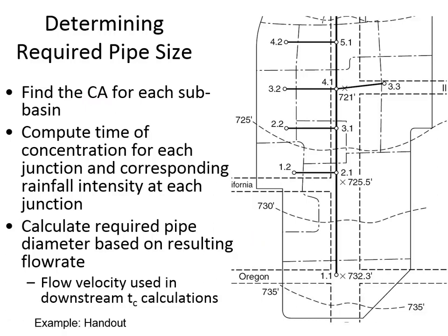And also in the example we're going to work, what's defined is the area, the slope of the pipe, the length of the pipe. We're going to go through a process of calculating what is the peak flow rate that will get to there, and then how long does it take to get through the pipe, because we know the size of the pipe is going to be calculated by us based on how big it needs to be to accommodate the flow.